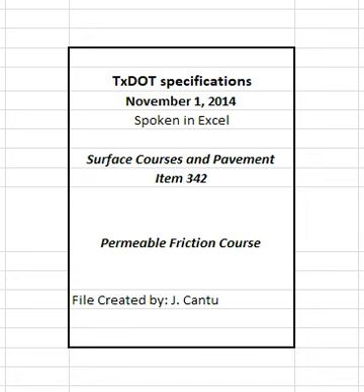Asphalt binder from RAP and RAS is designated as recycled asphalt binder. Calculate and ensure that the ratio of the recycled asphalt binder to total binder does not exceed the percentages shown in Table 2 during mixture design and HMA production when RAP or RAS is used. Use a separate cold feed bin for each stockpile of RAP and RAS during HMA production.